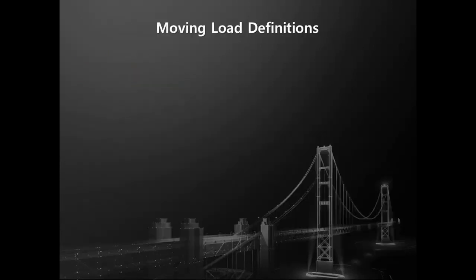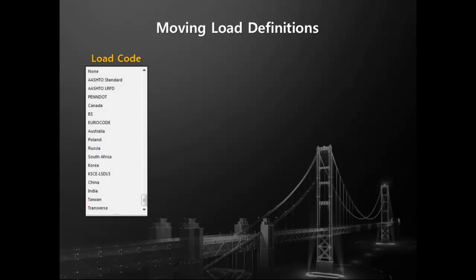Then another thing is moving load definitions. Again, for bridges, the vehicular load plays an important role. So just last year, depending on our client demand, we have gone for moving load definitions in accordance with the South African standard. First off, you select the load code, which in this case would be South Africa.